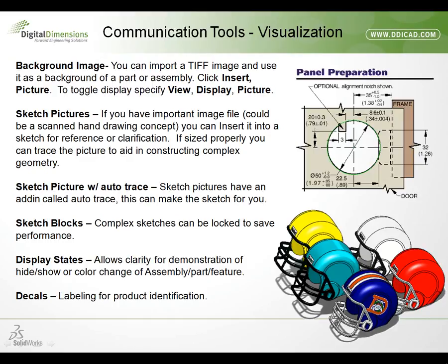A display state is visual-only properties for assemblies, and now new to SOLIDWORKS 2010, they've added the ability of display states at the part level. These display states, for the very same reason they made them in assemblies, they've brought to the part mode, so those of you using weldments will be able to take full advantage of display states in the same way that you would have otherwise in complex assemblies.